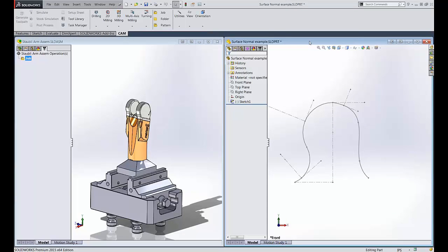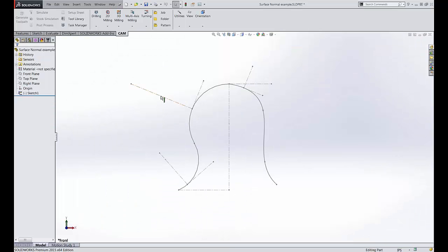Somewhere in here, I have a great example of why it's not tilting. What the multi-axis toolpath in there is doing is trying to maintain normal to a surface. And in here, I have a sketch, and hopefully I can move this. This is showing the surface normal. This is on an arc. This is on an internal arc. Here's the surface normal on a spline.